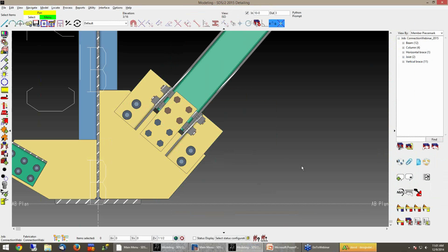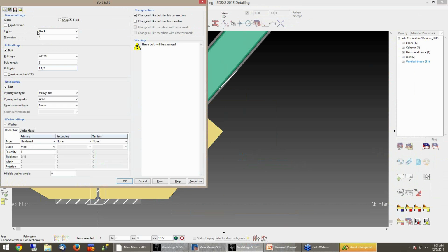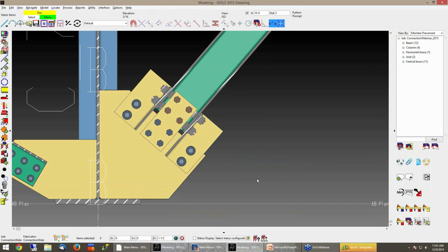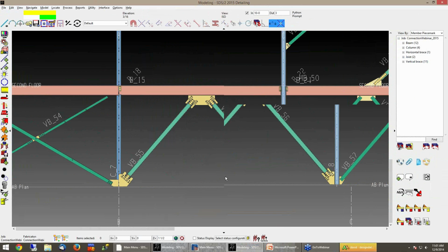And now you notice that the angles got larger, the bolts got larger. I believe we now have 1-inch bolts instead of 3/4 like we did before. Lessening the number of them, it required larger bolts to be used. So it's going to redesign around that.